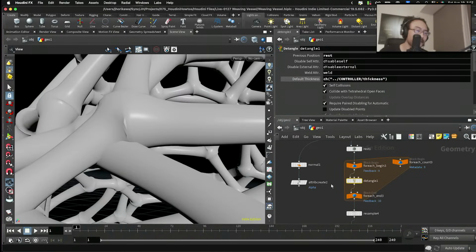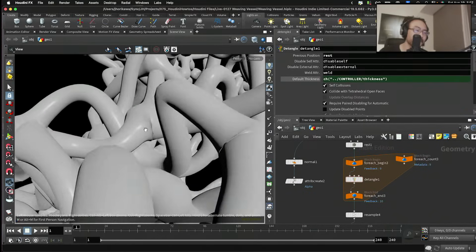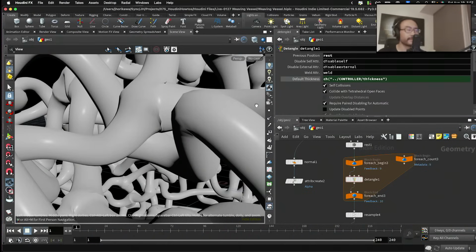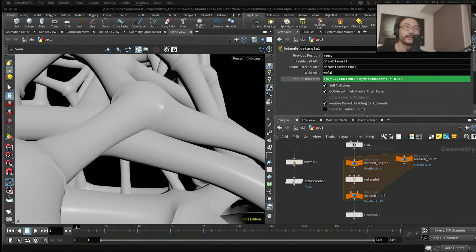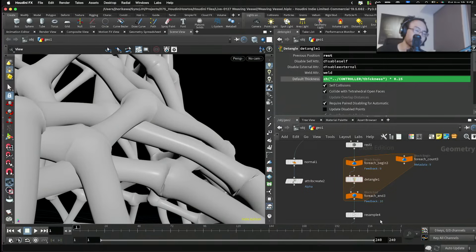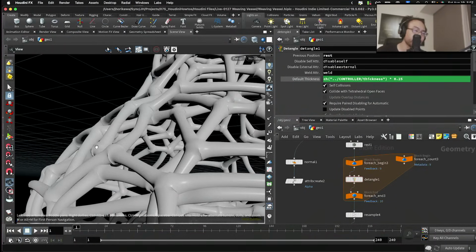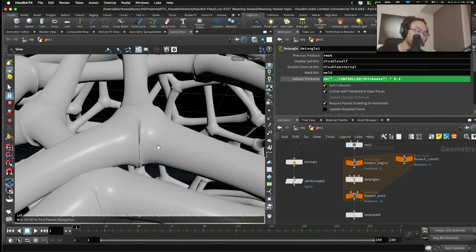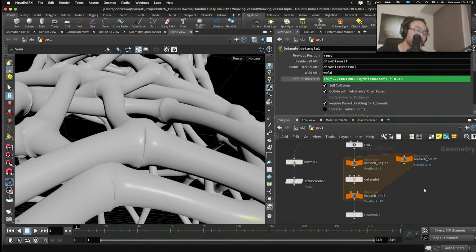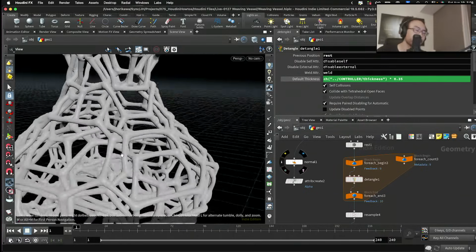But if I make it too high, it's going to make too much wobbles, too much avoidance of thin thicknesses, so repel. So I'm going to multiply this by 0.25 or some small number from the original thickness. I'm not sure what's the best value for this one. For now, I'm temporarily setting it to 0.25. And for now, it looks okay. I do see small touches here, so maybe I can still increase this a little bit. Yeah, a little bit more. Maybe somewhere around here.